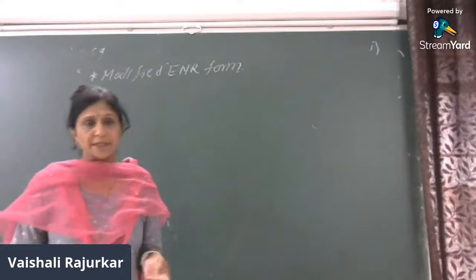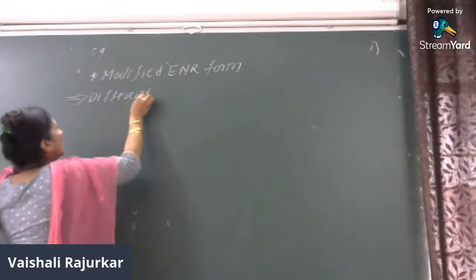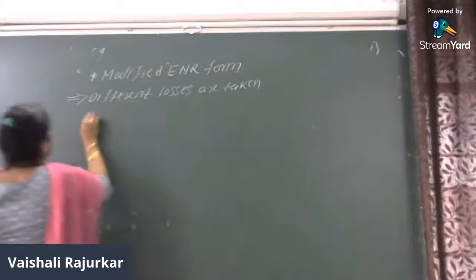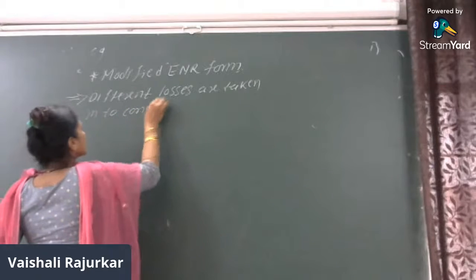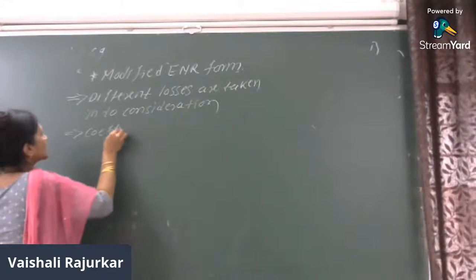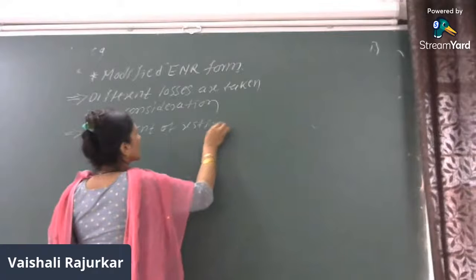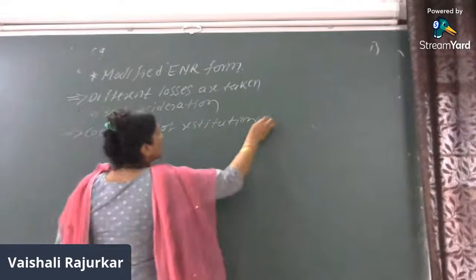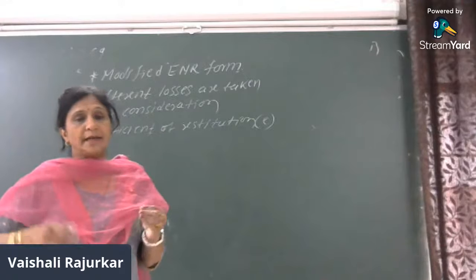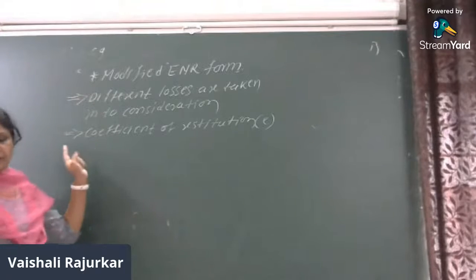Then the coefficient of restitution is also taken into consideration, and that is denoted by E. Coefficient of restitution means that due to the driving of the pile, there is a compression of the pile and the surrounding soil, and all that is taken care of by E, the coefficient of restitution.